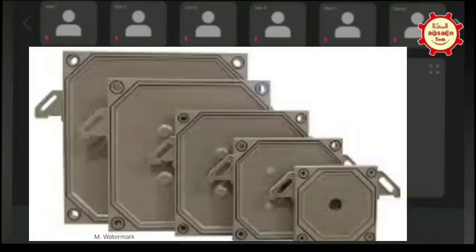So it cannot be done as a flat head like that. I can do it as a flat head, but the ligament efficiencies I have to provide, and then the thickness will be very, very high for a 2 meter flat head.